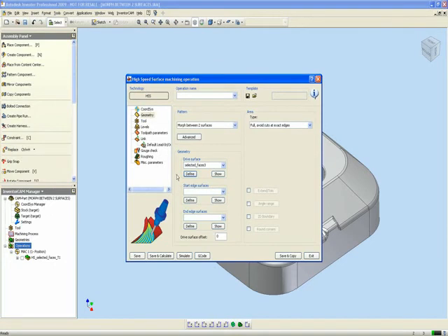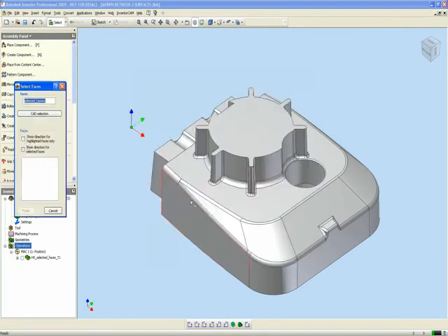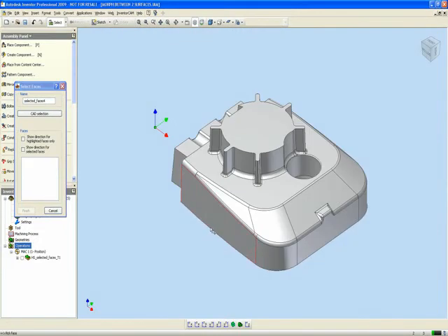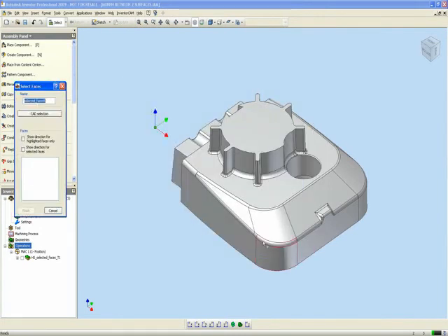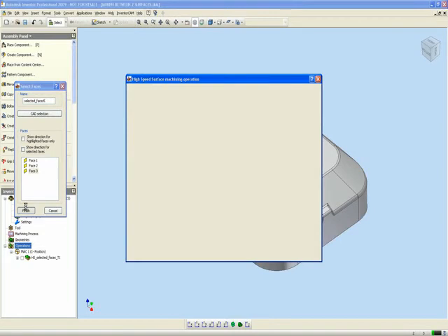And my start edge surface will be these surfaces on top over here. So I'll simply choose this surface over there and this surface over there. And for my end edge surfaces, I'll choose these three surfaces over here. This one, the adjacent one, and the last one over there. And I'll simply say finish.